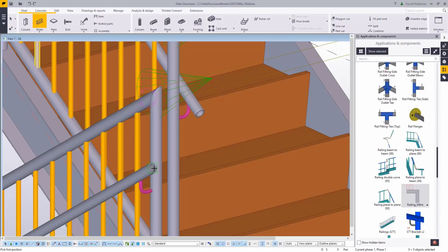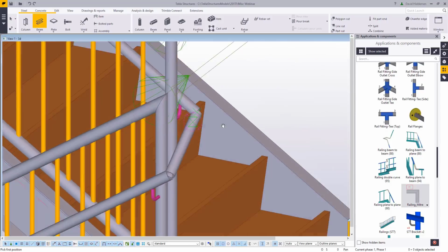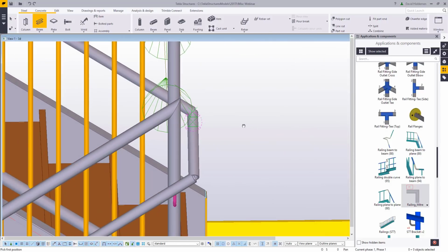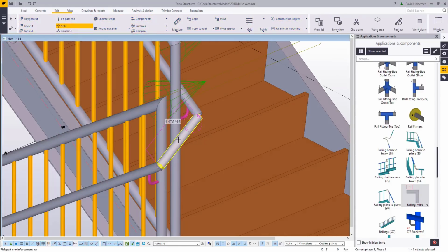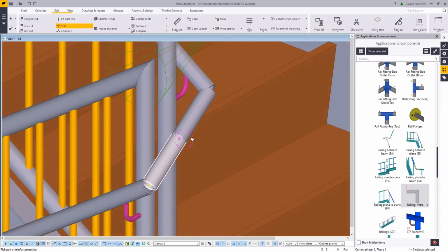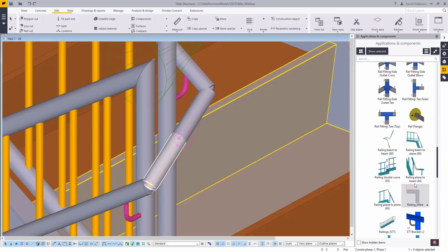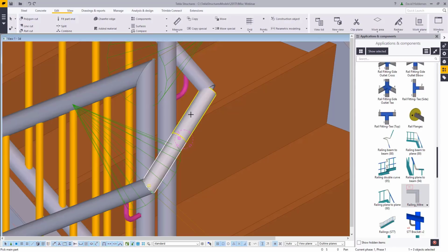Personal preference, though, again, is to just go ahead and click a part, or a beam part, to connect those two. I am going to add a split command, which is where I'm going to add a splice, or where I would have a splice. We do have a tool that will also do that, put in a solid insert or a smaller pipe insert if you desire. And then I'll just miter the corners of these again for simplicity's sake.